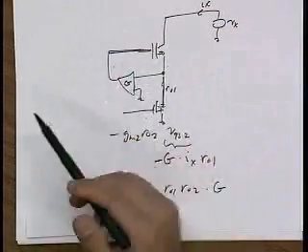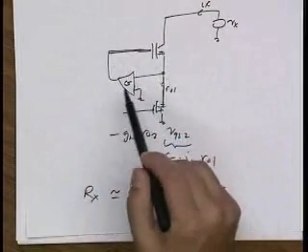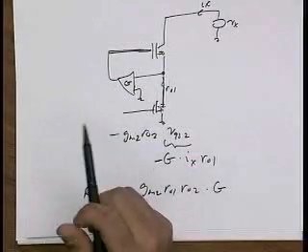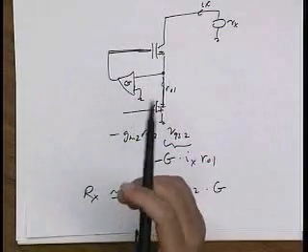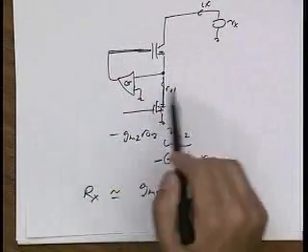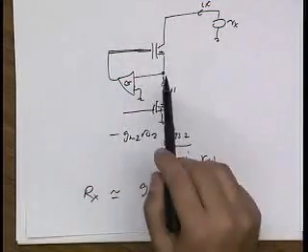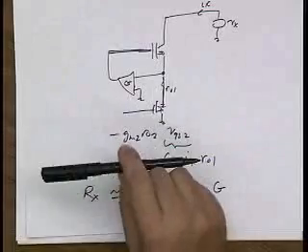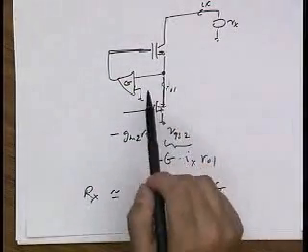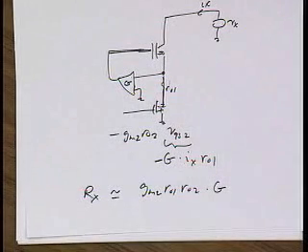Right? In fact, it's not so obvious. And one of the surprising results is that, in fact, no, you want to make this loop slower than your amplifier for stability reasons, not faster. So, in fact, stability is a concern. We have to look at it carefully, but it's not a showstopper. Otherwise we wouldn't be talking about this in this class. Compared to a regular cascode, though, what other potential issues do we have to watch out for?